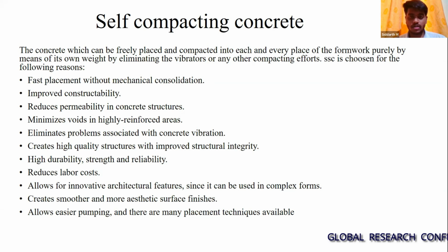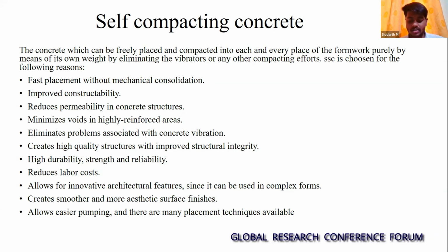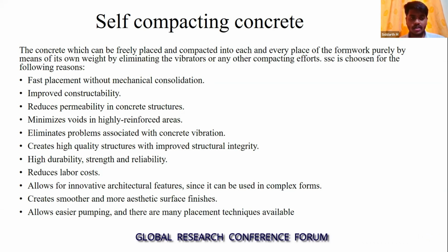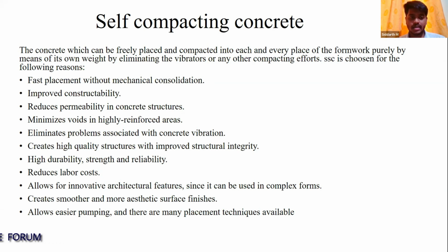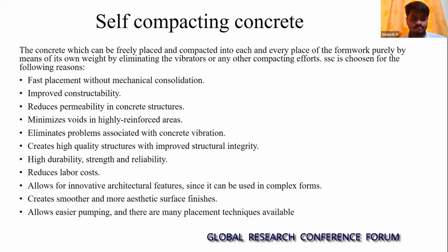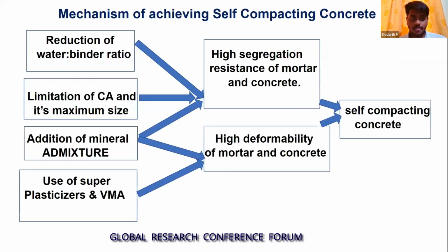SCC is chosen for the following reasons, because it has more advantages than the normal concrete. It has improved constructability, reduces permeability in concrete structures, minimizes voids in highly reinforced areas, is highly durable and strong, and reduces labor cost.